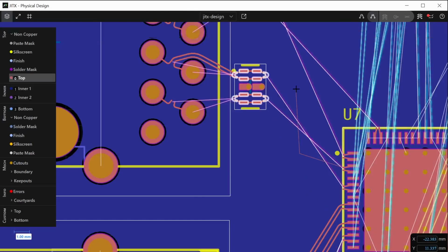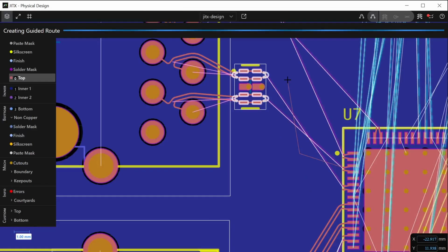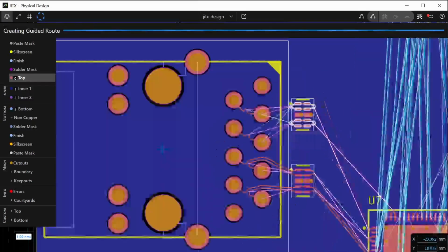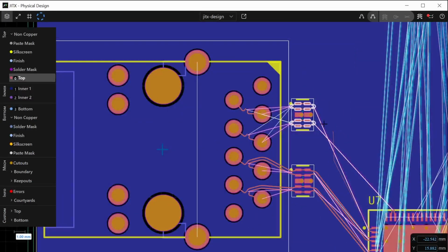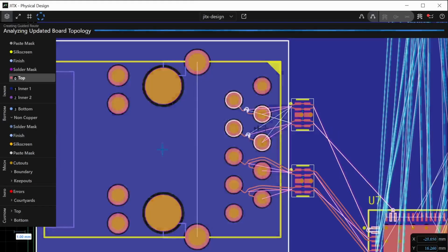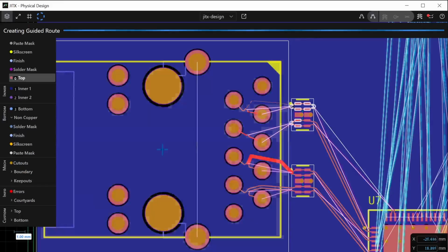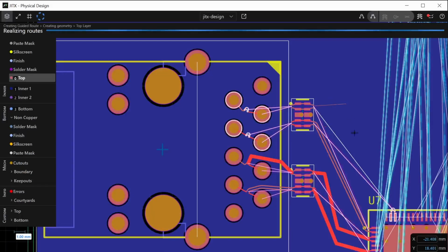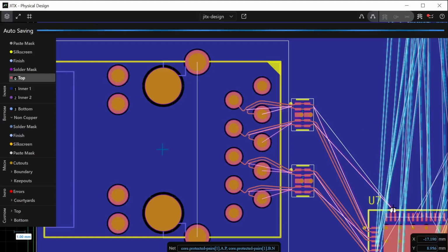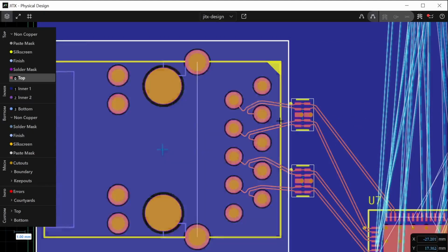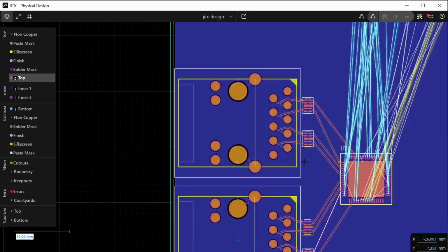Notice that sometimes when you route, the routes will change dimension as you assign the pins, and that's because it doesn't necessarily know what the rules will be before you actually have the circuit created. So that's like, if you use an FPGA pin as a clock, you'd have different routing rules for it, but you don't know which pin is a clock until you actually assign its function. So that's why you're seeing these dimension changes there.